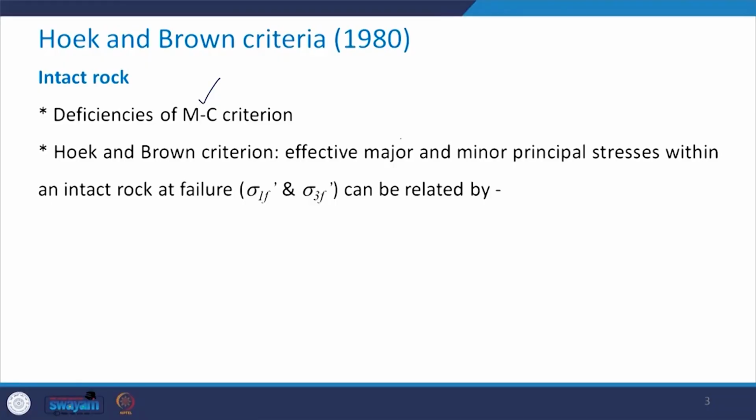If you recall our discussion with respect to this Mohr Coulomb criterion, we discussed that in case of the rock mass where the discontinuities are also present, it is not really possible to get the parameters of Mohr Coulomb failure criterion in terms of effective stresses. And therefore, we just left there with a big question of how to determine these parameters.